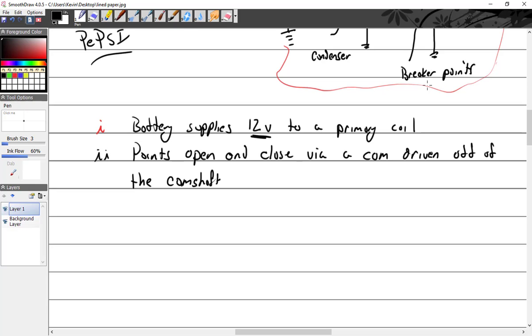That's the power stroke. So we have intake, compression, power. The last one is exhaust. On the intake stroke, the intake valve is open. On the compression stroke, it's closed. On the power stroke, they're closed. Then when it comes up on the exhaust stroke, the exhaust valve has to open up and let all that dirty, nasty air out. It pushes out that dirty, nasty air, the intake valve on the other side opens, and it comes back down.